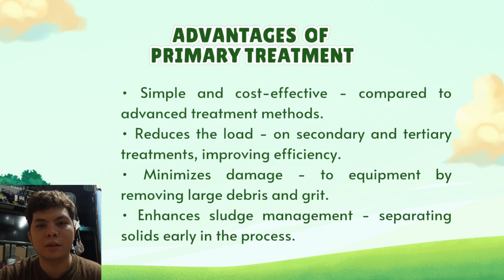The second one is reduces the load, because by eliminating a sizable amount of biochemical oxygen demand or BOD and suspended particles, it lessens the strain on subsequent treatment phases. For the third one, minimizes the damage, because large debris and grit are filtered out, preventing equipment clogging and lowering maintenance costs while simultaneously safeguarding the environment.